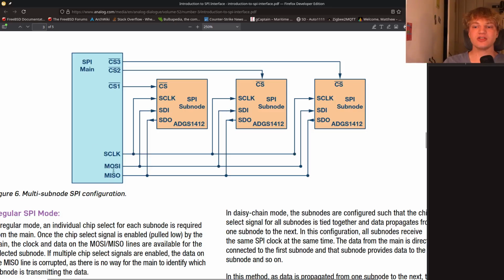So these two lines here, MOSI and MISO. MOSI stands for master out slave in, also main out secondary in, depending on the terminology, and MISO is the opposite, so master in slave out. So for instance, I'm just sending data here on this MOSI bus, right? And you'll notice that it's connected to all of these slaves over here. So every slave technically receives all the data that I ever send, but they ignore it if their chip select pin is not signaled correctly.